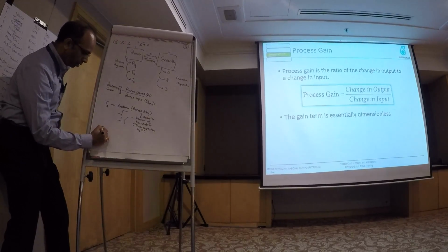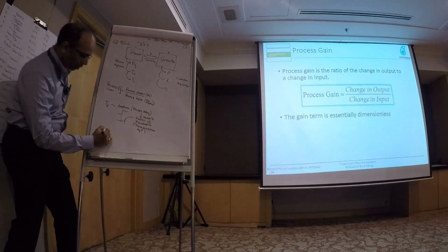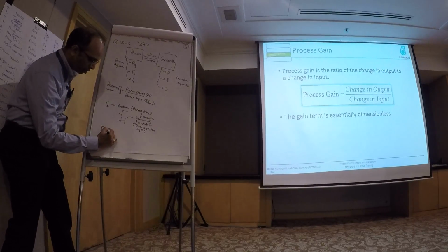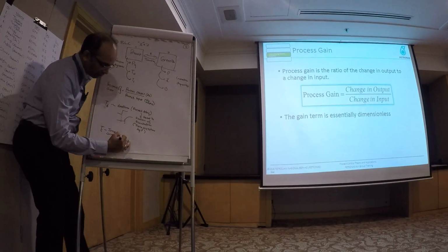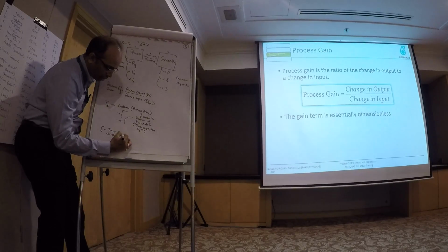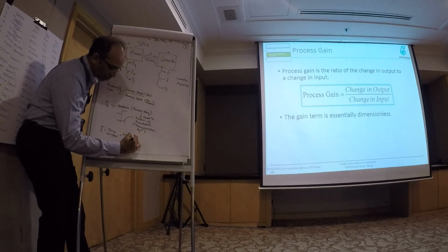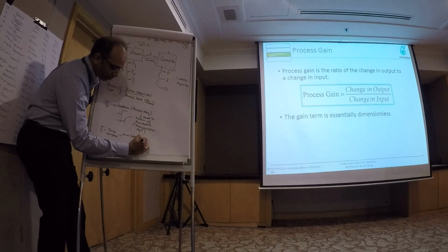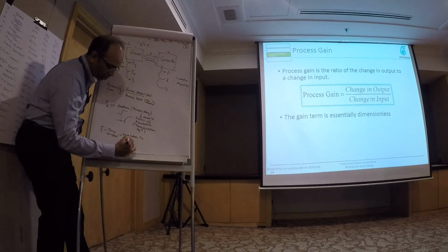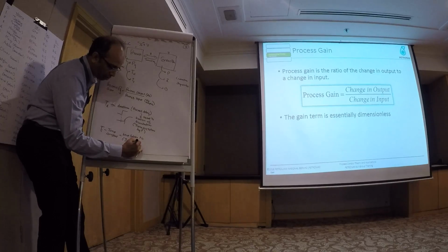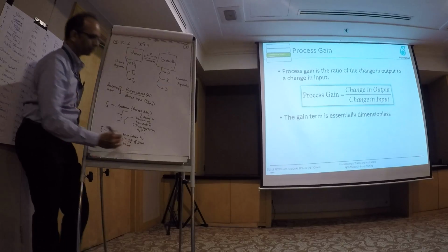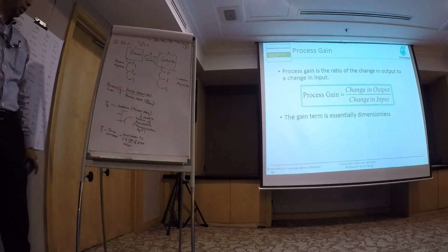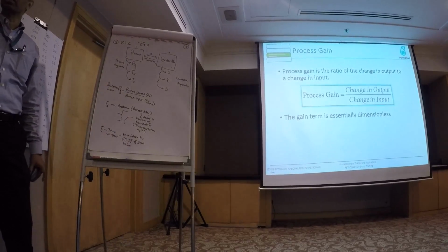The last one, which caused a bit of issue, was time constant, right? You can forget about everything I said, that it is time taken to reach, what's that magic number? 63.2% of final value. Okay? So process gain, dead time, time constant.